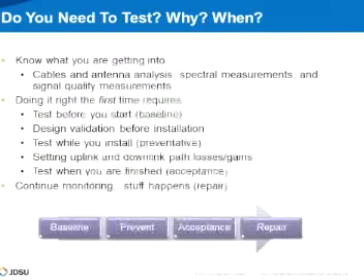Test while you install, that's all about being preventative. Making sure that you're doing things right the first time, so that you don't have to spend the time to go back and try to isolate what may be wrong if you see problems after you get it all turned up. Setting uplink and downlink path losses and gains. Again, this comes back to that dynamic range. Ideally, you want to be in the middle. You don't want to be too weak and you don't want to be too strong.